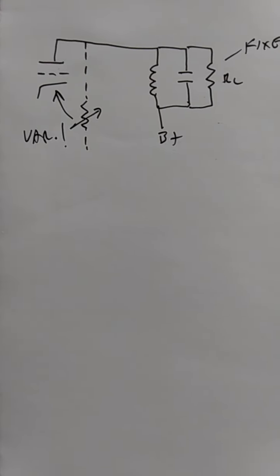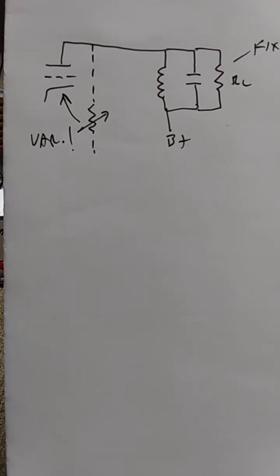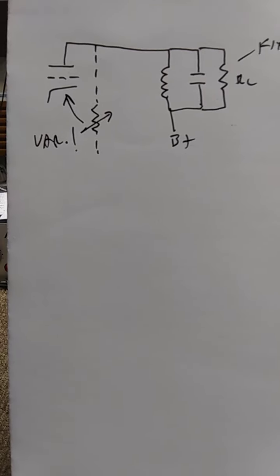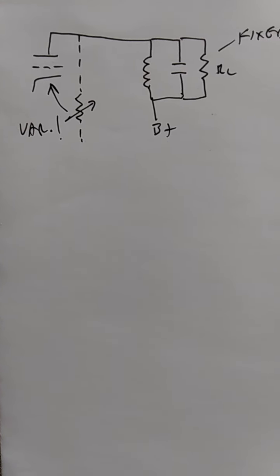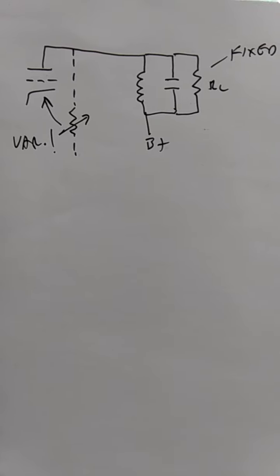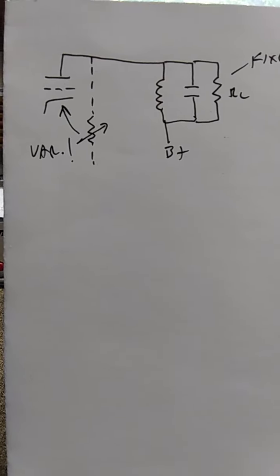The tube data, the Eimac data, especially the calculator, allows calculating power output for fundamental, second and third harmonics. But the harmonic power levels I calculated were something like 230 on the second and 30 on the third harmonic. They're way too high level for the normal amplifier working into a tuned network like a pi network.